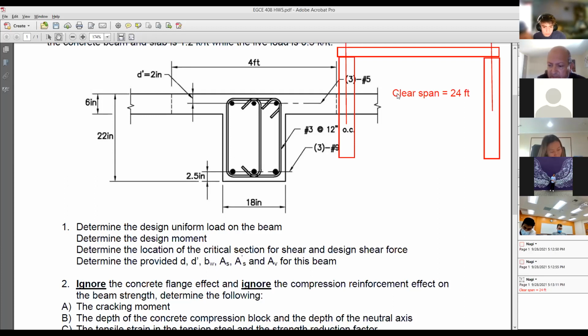Sorry, remember what the equation says? Can you ask that again? You know the equation, what does the equation say? Do you know? Oh, the tension is equal to 0.85 times f'c times the area. Yeah. And how much is the compression block depth A in this case? Sorry, what was that? How much is the compression block depth? A lowercase. How much value would you get for that?